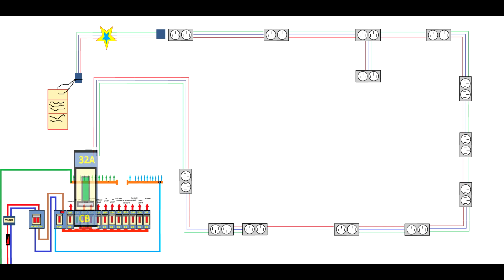If you cannot repair it, you might have to break the walls, and then you will put the socket back and reconnect the circuits, but then you have a problem. You have 32 amps for a circuit that is not a ring anymore because you broke the ring. So you isolate that part which is faulty until you repair it. Then obviously you have to turn off the power supply, and then you have to downgrade this circuit. You have 2.5 cables, as an example, not a ring circuit. You will have to apply the derating factor.